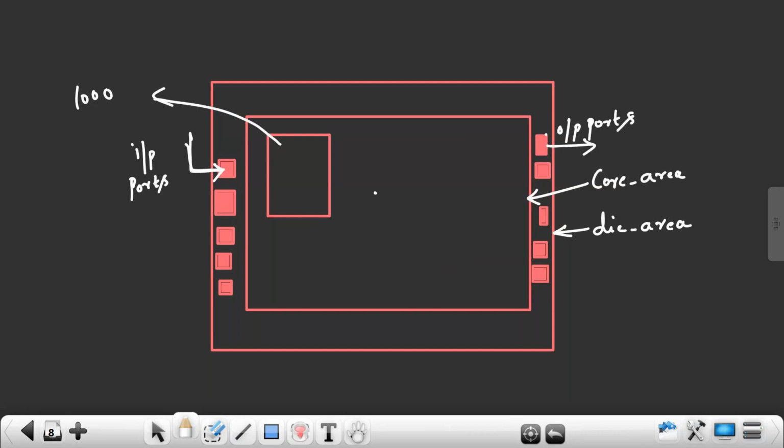Doing physical design without any constraints we can do easily, no problem in that. But doing physical design to meet these constraints, like less area, less power consumption, and high frequency of operation, that is difficult. That is challenging. So if I have a macro with 1000 cells in each, and I start using it in the Verilog code, synthesizing, doing physical design and optimization, it requires a lot of effort. Again, cell count will increase.